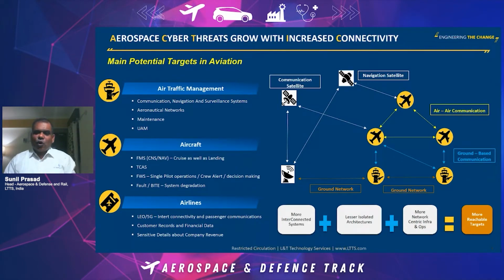All of these are being evolved as a single architecture, with fewer and fewer isolated, federated architectures. You now have integrated modular avionics. All new aircraft would have integrated IMA instead of a federated application. And not just that, you're now looking at the whole connected aircraft, with the ground communication, the aircraft, and what happens within the aircraft.